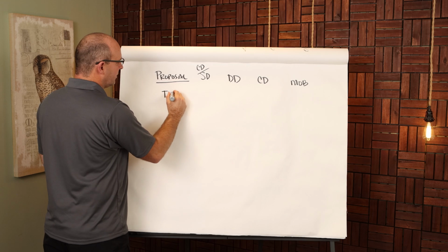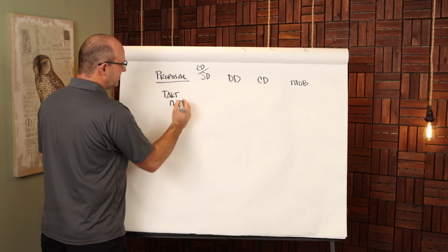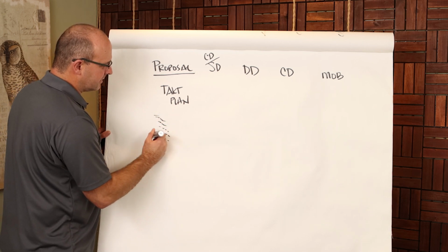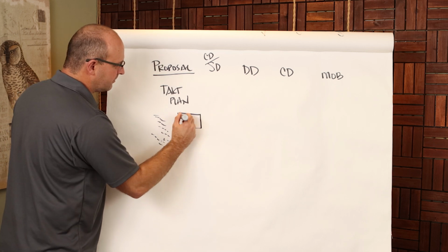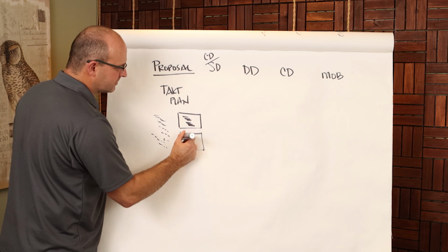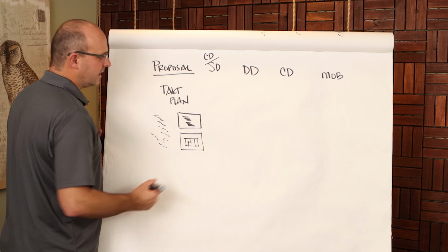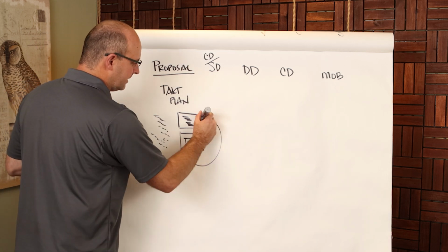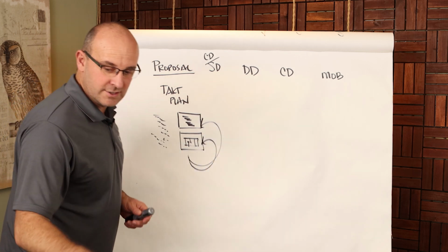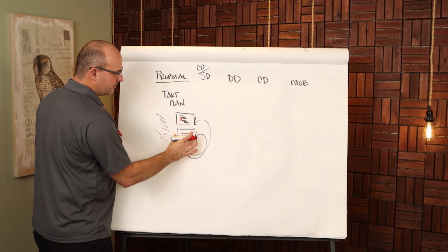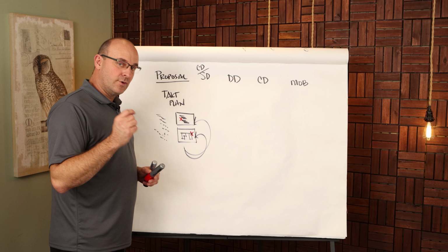First of all, in the proposal, my favorite place to start my Takt planning efforts is in the proposal phase. You know, versus having like a 53-page schedule that nobody on the team is going to read or understand. I want a single-page Takt plan that is clear, that is understandable, and I want to also see those zone maps, right? So that I can communicate to the owner. Now, in the proposal phase, you're going to detail this out accurately, and you're going to start to find the problems in the overall project, not only from a timeline standpoint, but from a spatial standpoint, and you're going to start solving those.